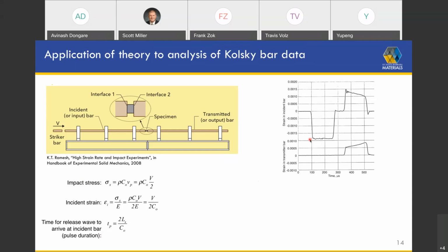where you have phonon drag mechanisms that operate. This is at strain rates of about 10 to the 3. They're not super high, but they're high. You're starting to kick in other mechanisms that retard the movement of dislocations. Now, by the way, those phonon effects are going to be present in all solid engineering materials. So you'll find invariably that all engineering materials, when you get beyond about 10 to the 3 per second, they're all going to exhibit quite a high strain rate sensitivity.